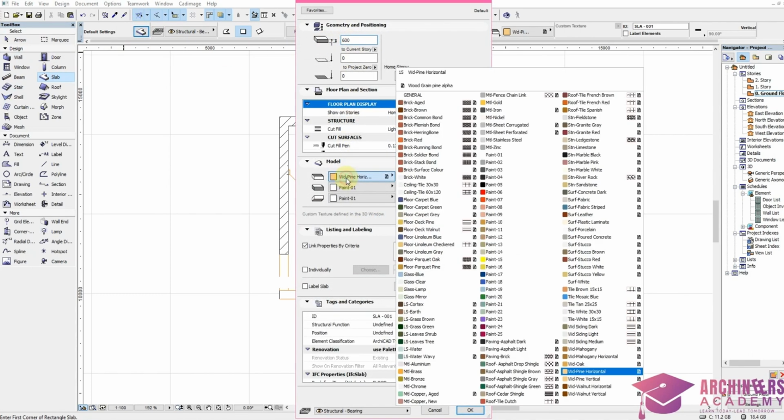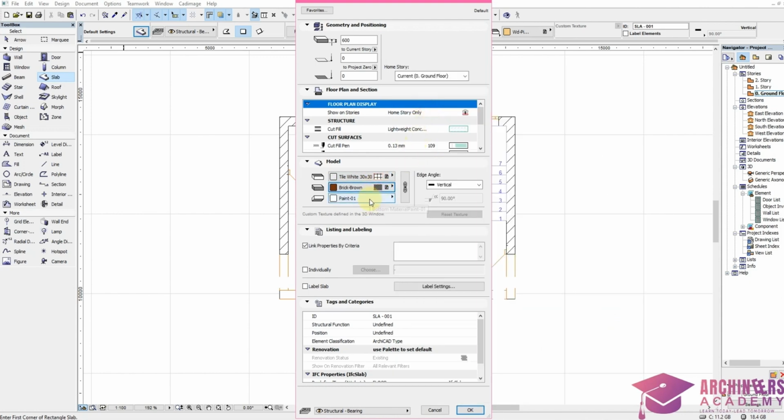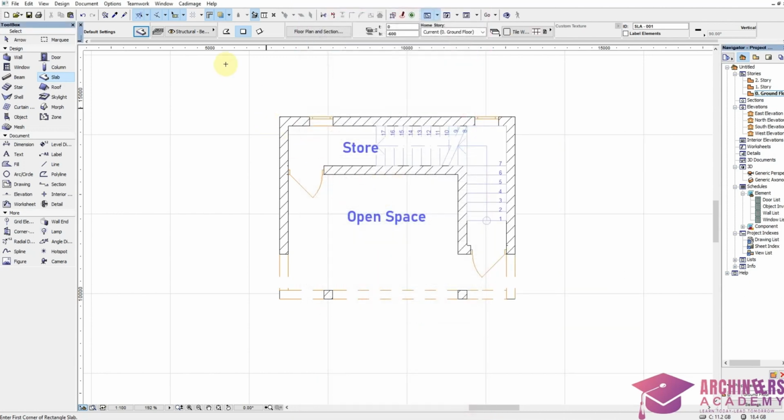The top slab can be made of tiles. Look for a tile material to use. The side part can be made of brick. Then the under edge, then click OK. Since it's squared, you can make it of this geometric metal rectangle. Place it, come over to the upper floor plan.